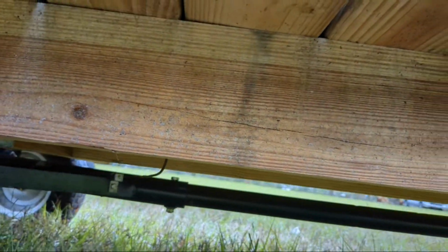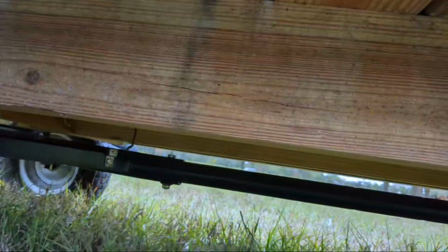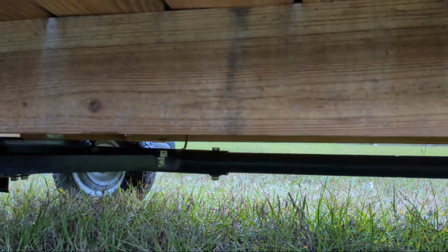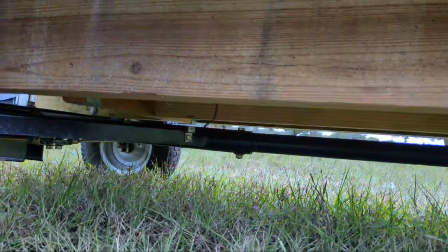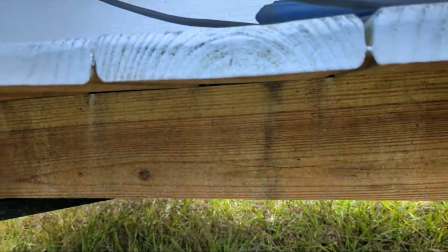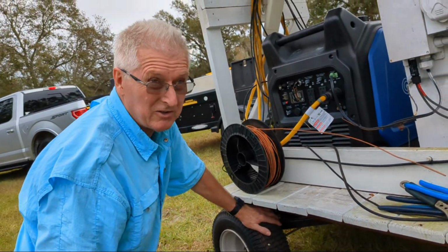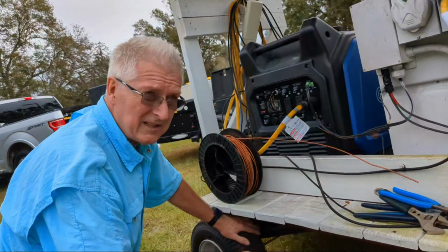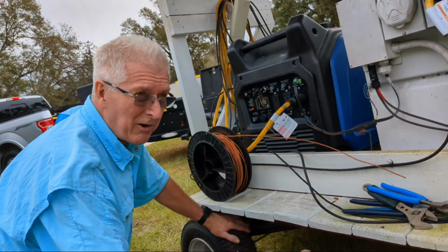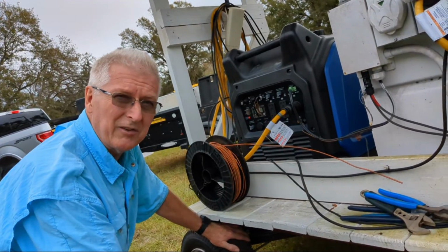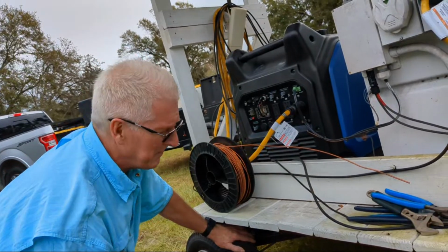Well, it's connected to the chassis of the trailer down here. Yeah, okay. So what we don't want to do is go down here. In theory, this trailer should be bonded to earth. Right now, we're using the chassis of the trailer like we would on a truck. The truck has wheels and an electrical system. But on a truck or your car, the chassis has a polarity to it. In North America, it's negative. So the entire vehicle is negative, at 12 volts.